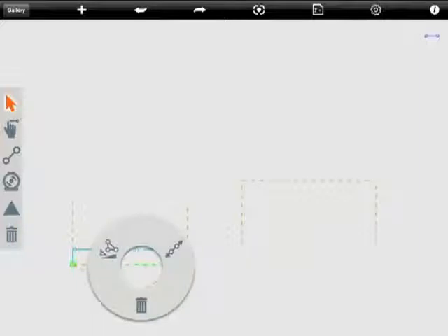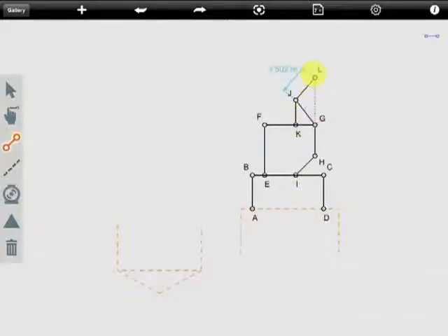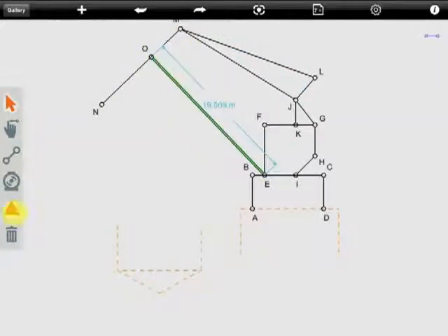Notice that tooltips display for context menu commands after a brief delay. Tap the tooltips to get more information for that particular command. Tap Create Element to draw a line diagram. Tap, hold, and drag to create. Dimensions are automatically created as you sketch.